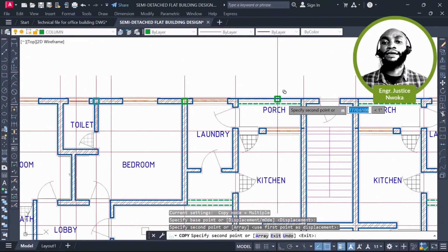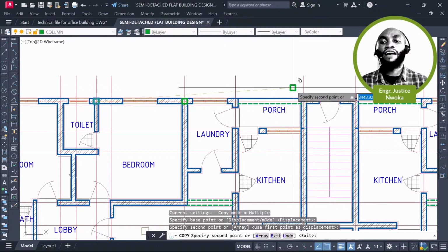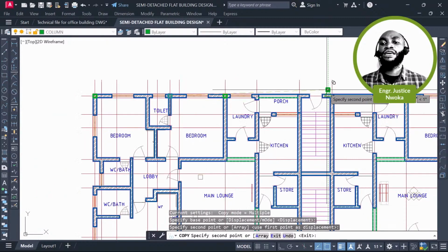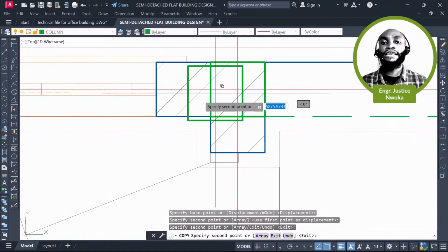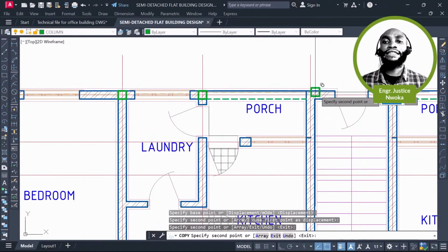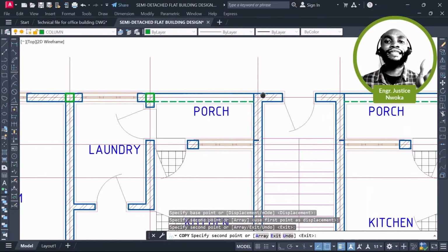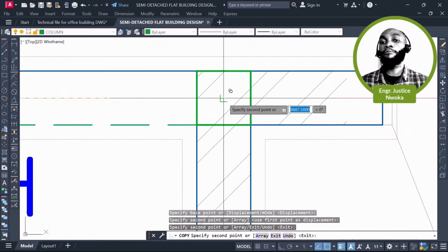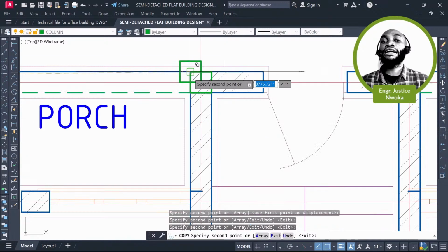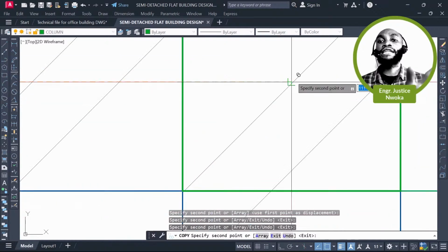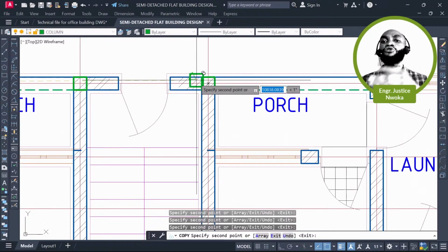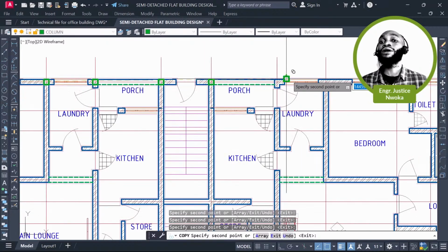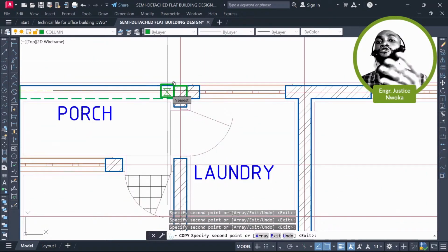Yes, place your columns first, and after that we will check whether they are more than 6 meters. So just place your column right now. Let that distance guide you on how to place your columns, because as a structural engineer, it is you who decides where to place your columns and which columns will be able to carry the structure. So you are the engineer who decides where to place them, with 6 meters as the guide for younger engineers.